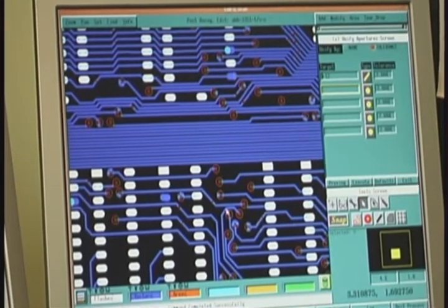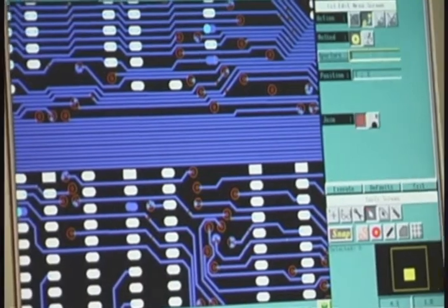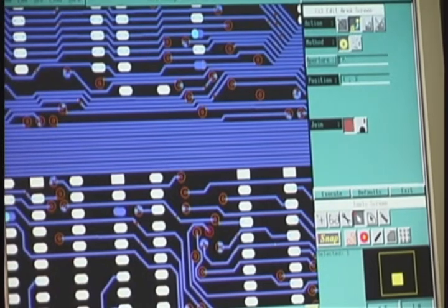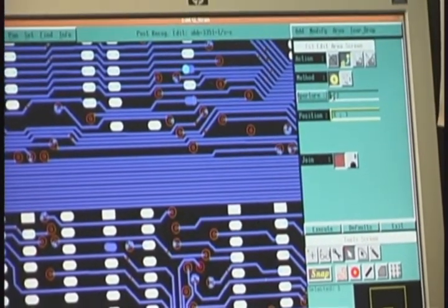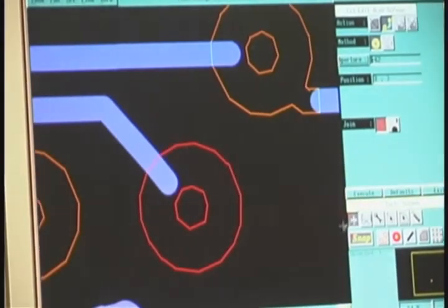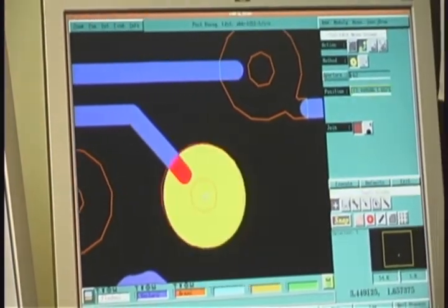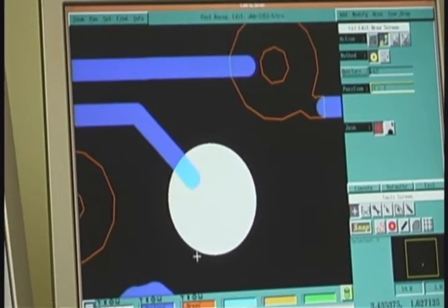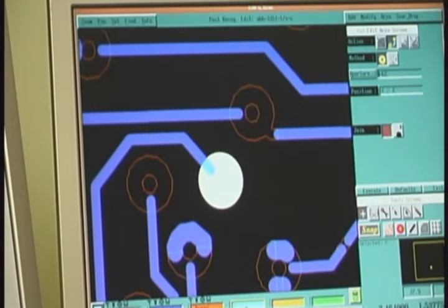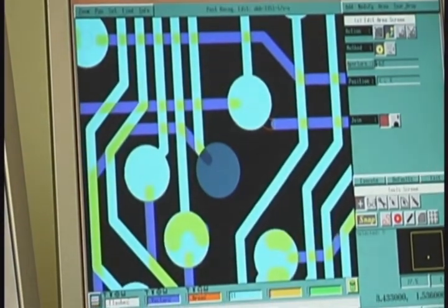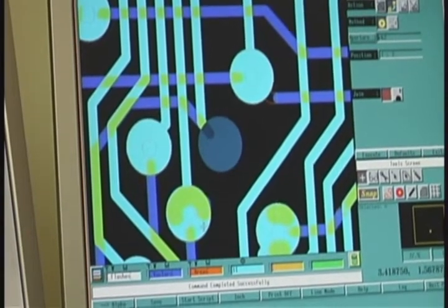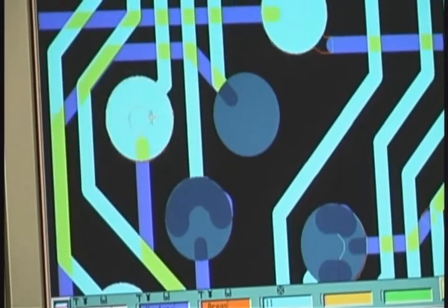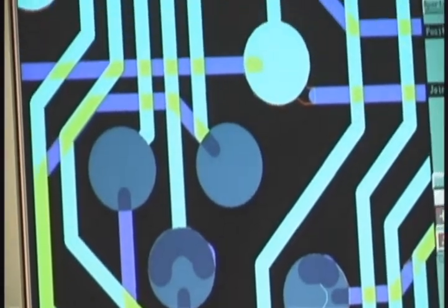In this case, we will use an editing command to replace the pads, and that will be a round 62 flash. We have different options to do this. We can either place it manually like so and execute it, or you can use your other layer and snap to that other layer and just move through and replace the pads that way.